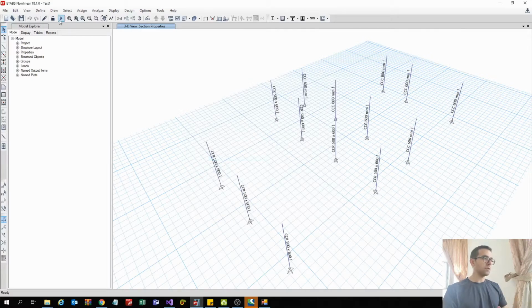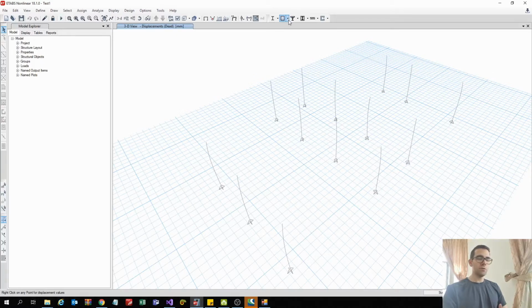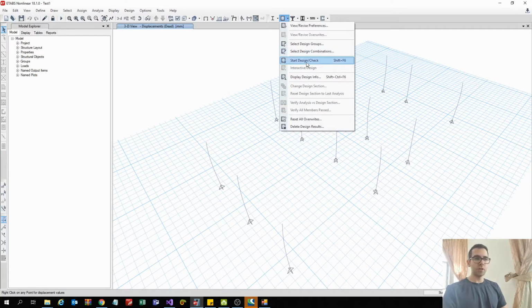Now, is that what I would normally do? I would run the model, as you can see, and this should be a relatively quick model. It's a small one. And I would look at what it is giving me for the reinforcement when I run concrete design. Now, the Autoless, if you've used it, or if you haven't, that's a personal choice for the engineer, gives you the smallest cross section. So now you want to know what reinforcement goes with it. Do you need to actually up the section?